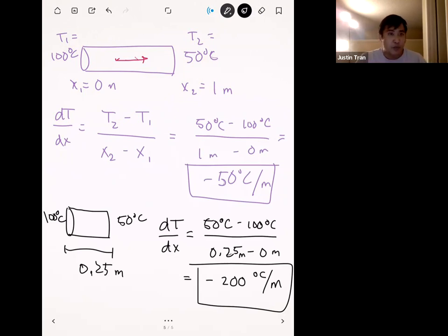And so I think that's an important thing to remember with that gradient. People think about that temperature gradient as purely a difference in temperature. But the distance over which that difference in temperature occurs makes a big difference as well. Both that distance and the temperature difference make an impact on the computation of the gradient. Okay. All right, any questions on this?